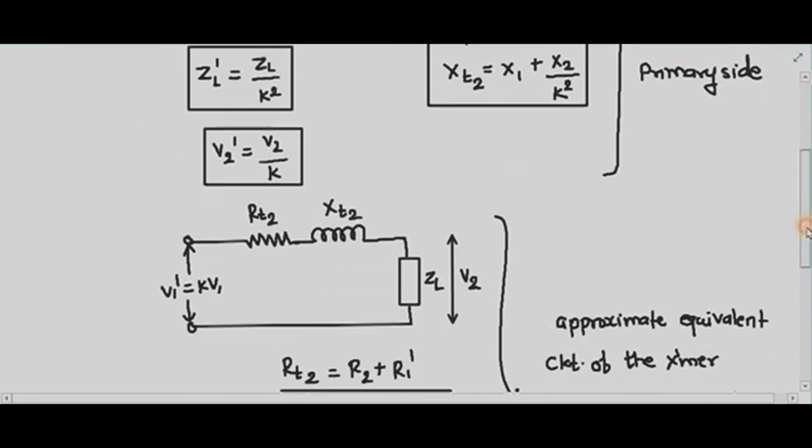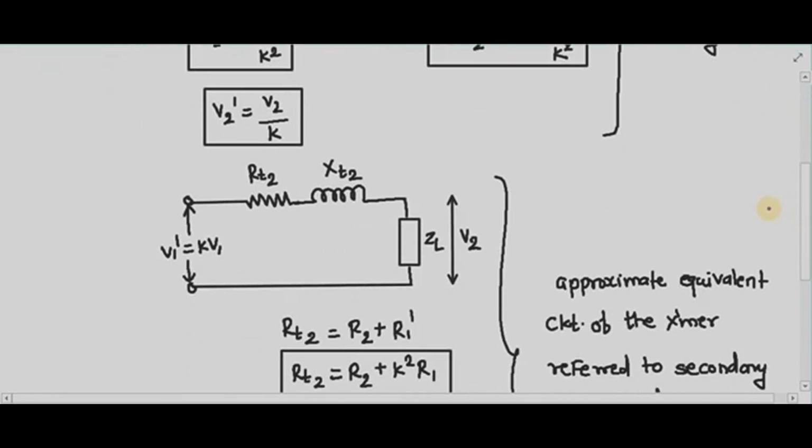So we know that the terminal voltage of a cell is always less than the EMF, right? The terminal voltage of the cell is always less than the EMF if my cell delivers current to the load. Why? Because there is some voltage drop caused by the internal resistance of the cell.